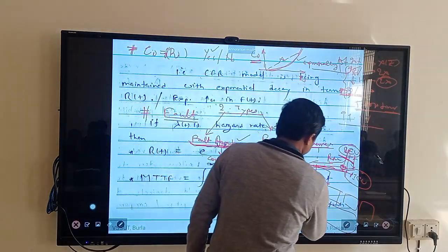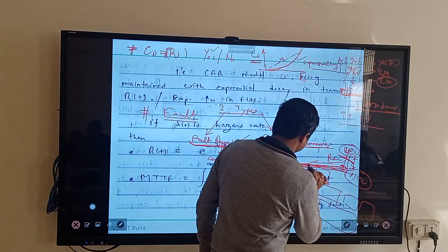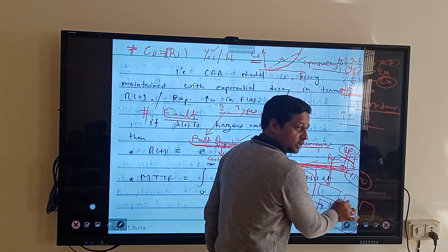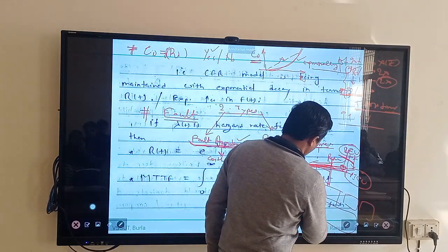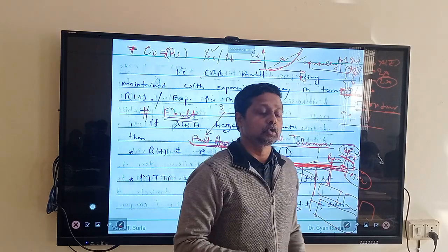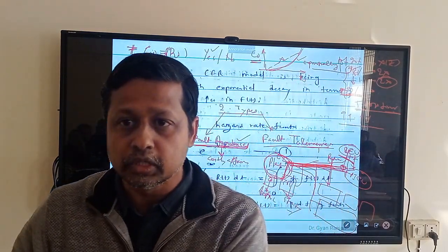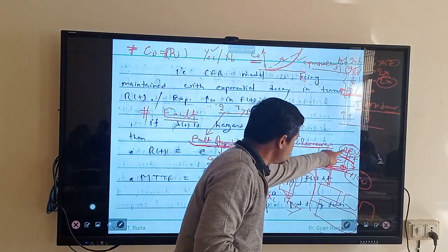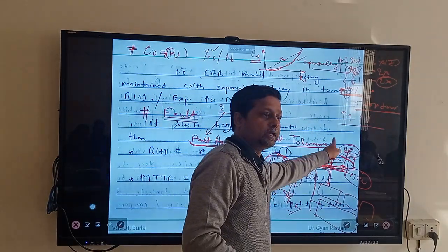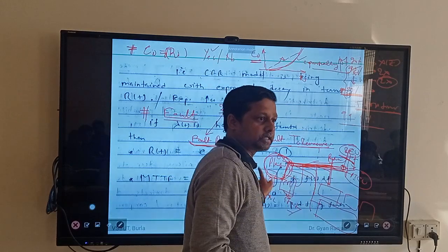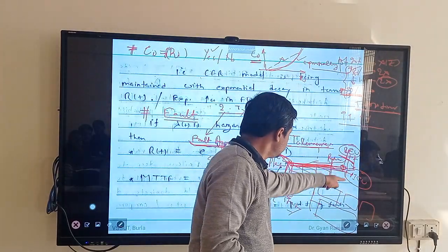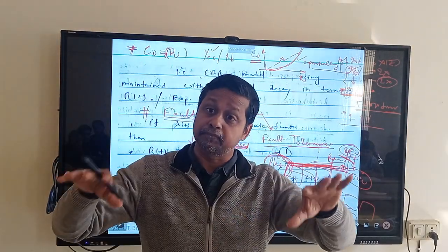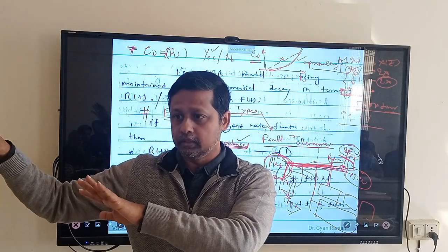Now, during this line, if this line is common up to a certain distance, you are going to entertain 4 sections. Understand? 4 different sections. And if this line is common up to a certain distance, right? Why did we keep it common? Not only to reduce cost, but because I am establishing a system, it's a marriage of a number of different kinds of components. So the nature of every component is different. Maintenance cycle of every component is different. Reliability of each and every component is different. And these all together have established a system with a different rate of availability or reliability. Are you getting my point?